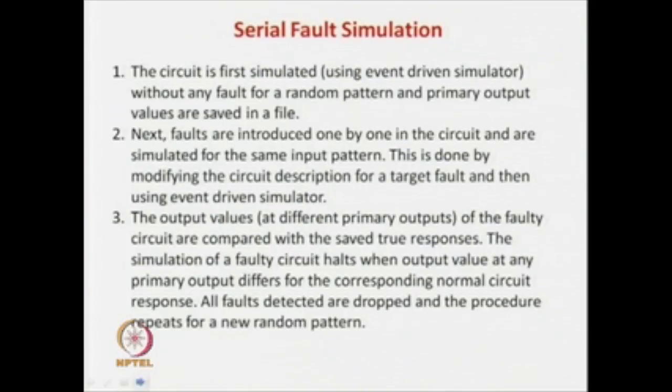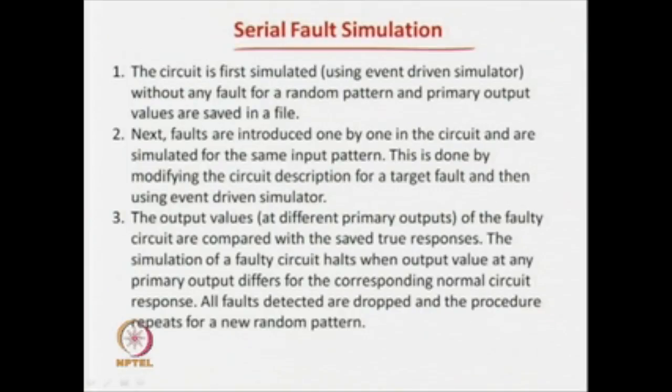So first we are going to see a very simple fault simulation algorithm, which is called the serial fault simulation. That is the very simplest one. In this case, you apply a pattern, then take one fault and see if the fault is detected by the pattern. If so, the fault is dropped, and that fault is considered already tested.